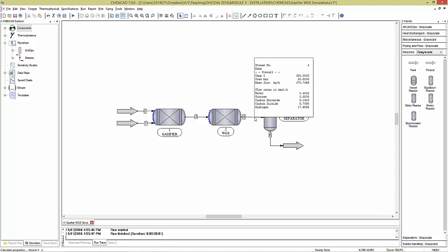What you would essentially do here is you would come and look at your H2 to CO ratio. As you can see, our carbon monoxide is 6, our hydrogen is 17. This is still way above 2, because if it was 2, our hydrogen was just supposed to be around 12 point something, 12.4, because there we have 6.2. So which means that in our direction, remember we said we are going to be producing CO2, and CO2 is favored by slightly higher temperature. So let's increase the temperature because we want to be using up hydrogen.